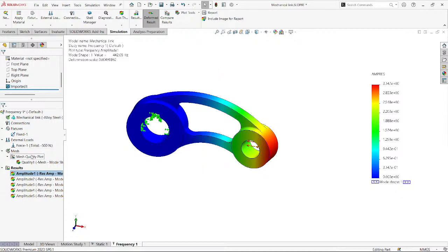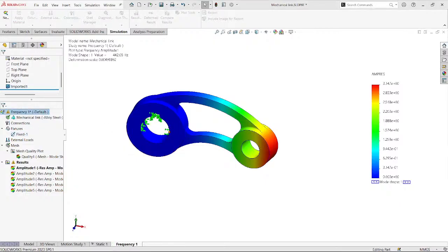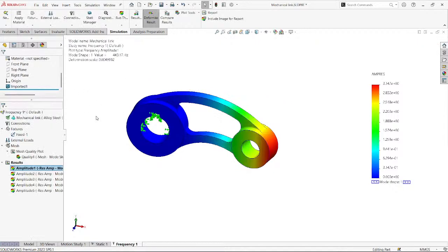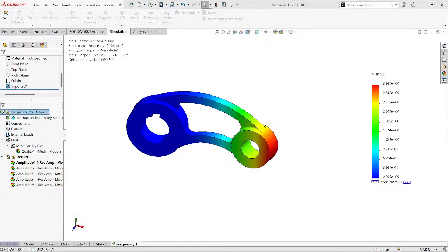Now here what I can do is I can simply delete this load case, and let me also delete the... no, let it be. So let's try to run without the load case. We have the boundary condition where we try to fix this, and with respect to this fixture, we will see what we get. Ensure that it is the same. Now I can even show you guys that we can simply remove the fixture and directly run this as free. There are no boundary conditions at all on the model.